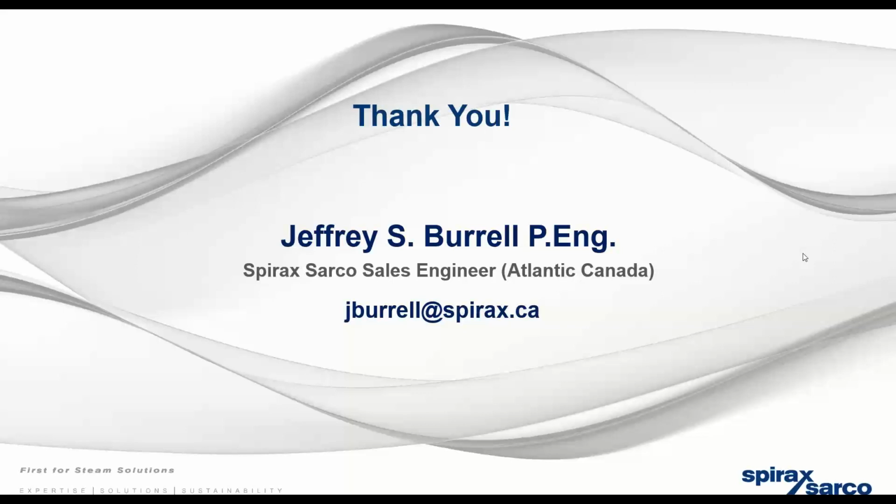Actually, I was just going to say, Jeff, we've had this issue where customers have used spring check valves with a really high cracking pressure, some as high as 10 to 12 psig. They were using them on low pressure systems, which meant the condensate just backed up. So we use spring-loaded piston check valves most of the time, and our most recommended are disc check valves because they have very, very minimal cracking pressure.